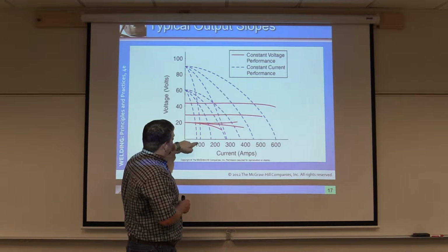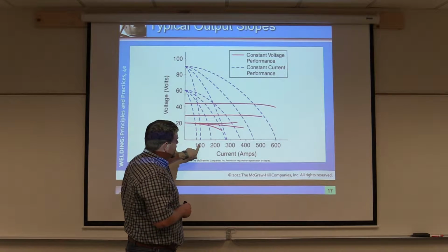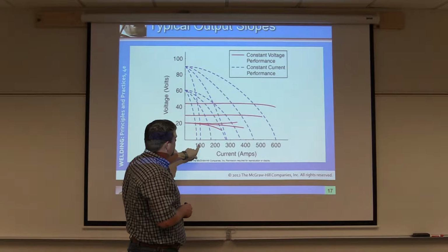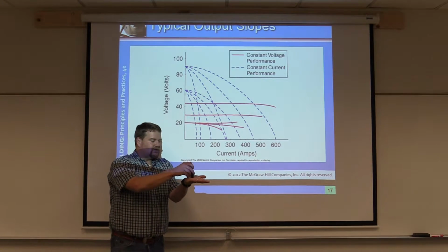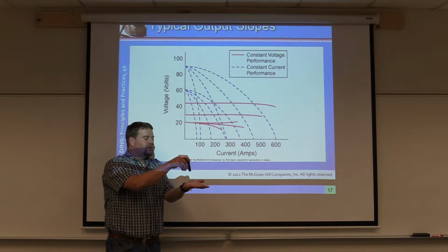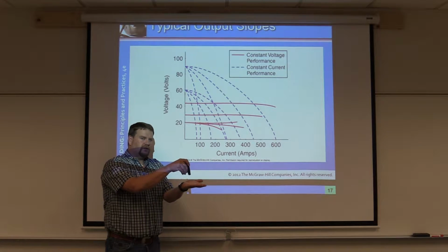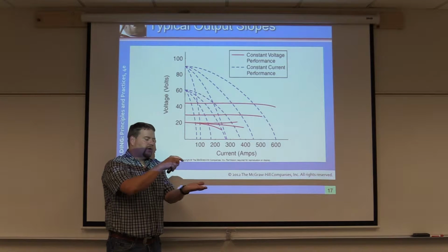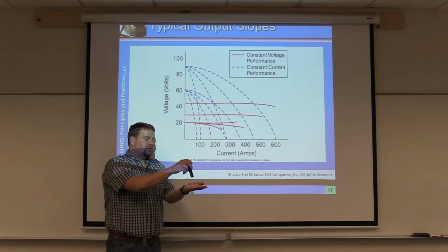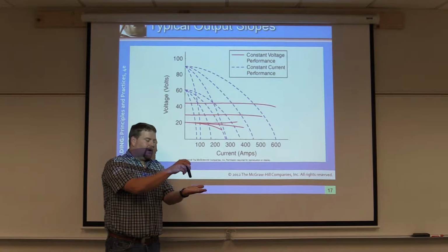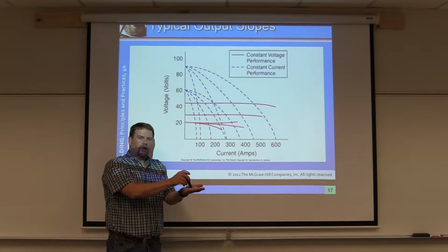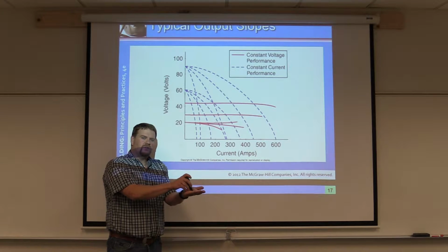Okay? Now, on our amp curve, it's going to be very similar. What happens if we lift our stick electrode off the workpiece? It increases as well because it's trying to drive the amperage up to bridge the gap. So it's taking the amps higher, then right back down to where you originally set it.